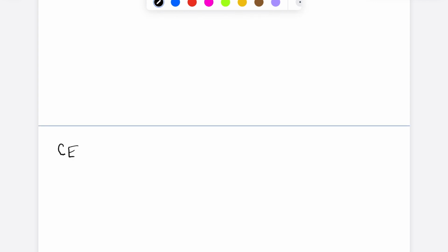And so that brings us to the topic of centroids. Centroids are a weighted average, again, like center of gravity or center of mass, but now we're weighting with a geometric property, which can be area or volume. So let's try to write a definition for centroid. I'm just looking for how your textbook defines it.